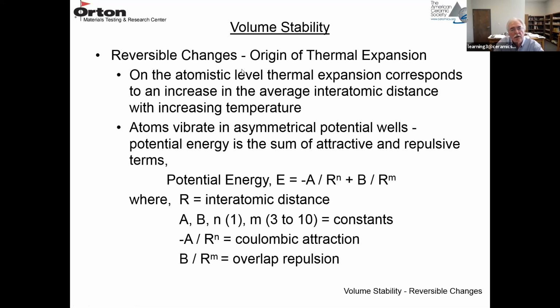So why do materials like refractories expand? What's the origin of thermal expansion? On the atomistic level, thermal expansion just corresponds to an increase in interatomic separation distance as you increase the temperature.